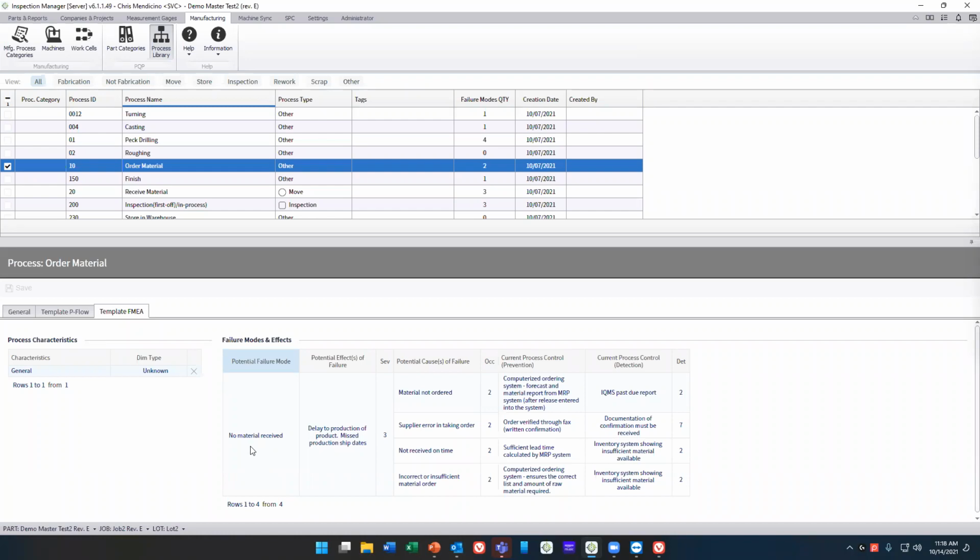And then during the implementation phase, we work with you to pick a couple of parts, like 1, 2, 3 part numbers, and we build out the FMEA content for those and start with that. So what are all the operations and processes that those parts flow through? Let's build those out and templatize that content first so we can build FMEAs for those particular parts. And then on the 4th part, the 5th part, it becomes less work because you're going to see more repeat operations and processes.